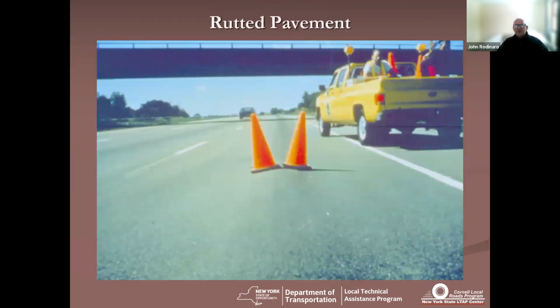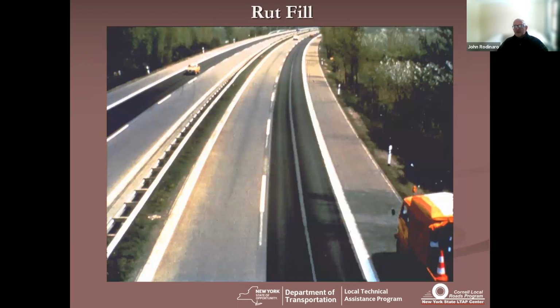And here's an important thing about microsurfacing. It was developed in Germany to deal with ruts on the Autobahn, and you can see all these nice channels in the wheel pass. So what they do is they put 2 V-shaped units in the back of the screed, and that channels the microsurfacing material into those ruts, and it fills them right up to the existing surface of the pavement.